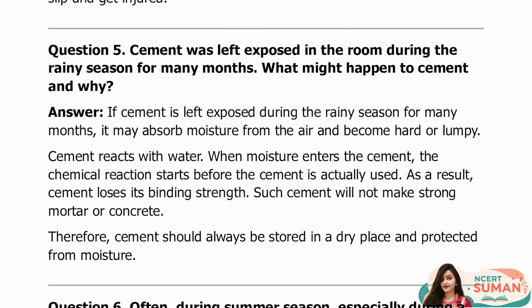As a result, cement loses its binding strength. Such cement will not make strong mortar or concrete. Therefore, cement should always be stored in a dry place and protected from moisture.